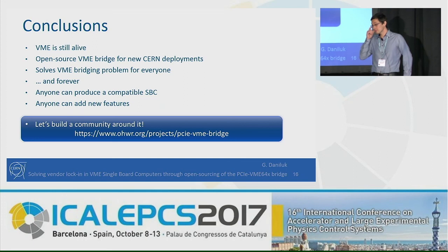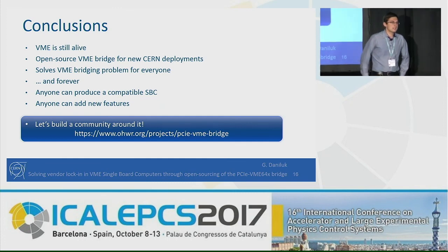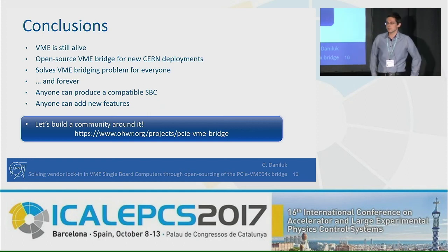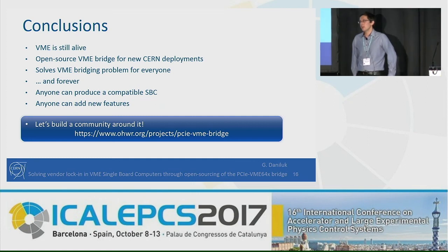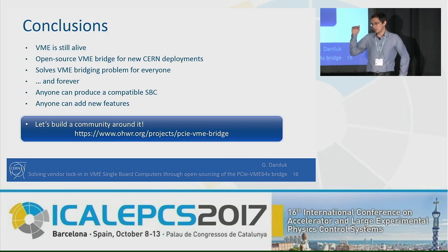So did you preserve the software interface? Is it still compatible with the TSI 148? For example, instead of Linux, we were using RTEMS. Would we need to make any software modifications to use your chip? Actually, for the MEN A20, so for the TSI 148 at CERN, we had our CERN driver for it, and what one of our colleagues did was write a wrapper kernel module that preserves the original interface and then translates it to the MEN drivers for this new bridge.